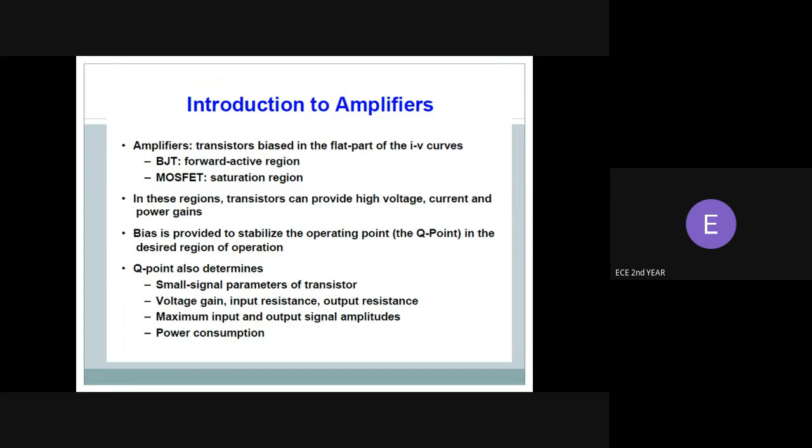In common emitter or grounded emitter configuration, the input signal is applied between the base and emitter, while the output is taken from between the collector and emitter as shown. This type of configuration is the most commonly used circuit for transistor-based amplifiers and represents the normal method of bipolar transistor connection. The common emitter amplifier configuration produces a high current and power gain.